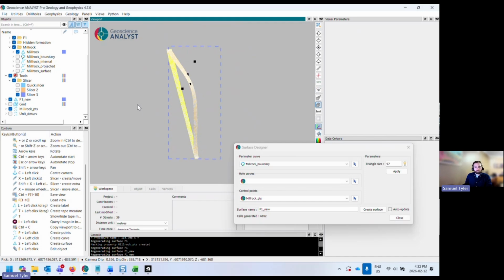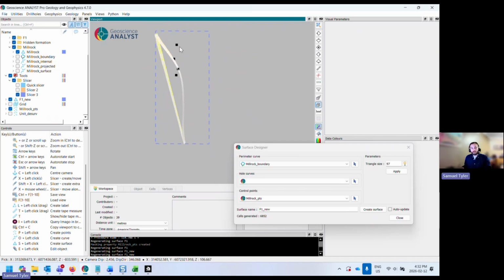Okay, so this isn't really how I'd leave this. Basically, that bottom projection is really affecting the shape of the surface and introducing this near vertical roll. That isn't how I would expect that to continue. I have a known point here. We have known points where the drill holes intercepted the surface. What we'll want to do is continue in that same projection and bring those bottom projected lines over to the right a bit.